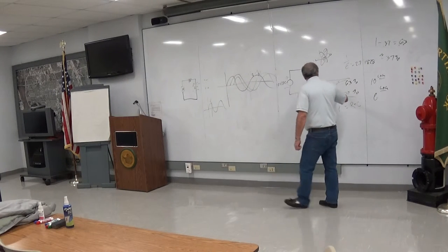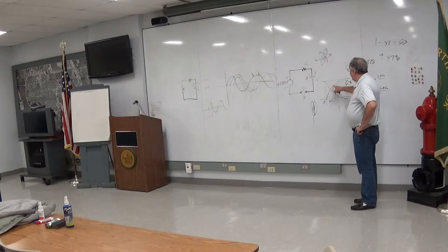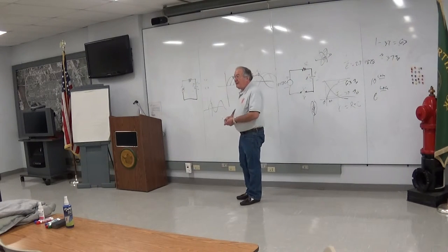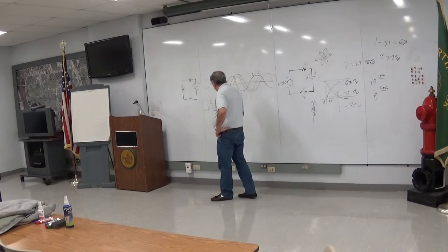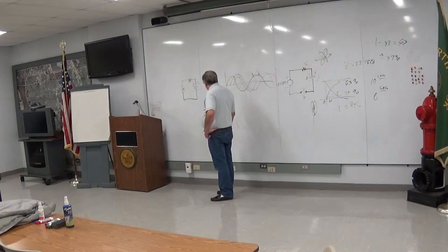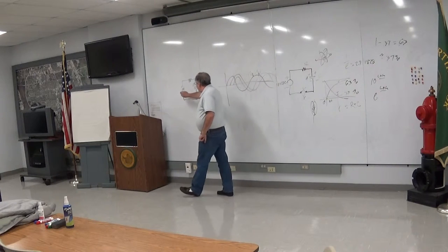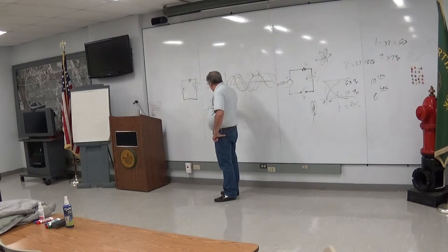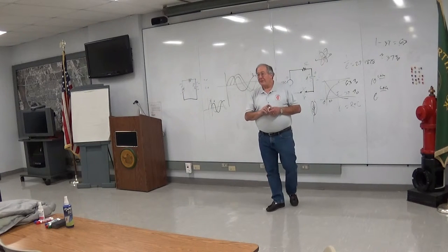But there's this time delay. It took until this period of time for the voltage to build up. It took this period of time, because of the charging up, for the current to decay down. So what's going to happen here is, if you have a capacitor here, immediately when you put your voltage source to work, this is the current flow. And starting 90, it actually turns out, if you look at the timing of this, exactly 90 degrees later, there's your current, this will be your voltage. The current will lead the voltage.